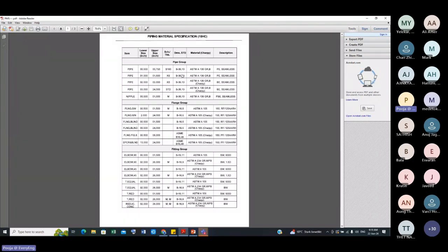And then I cannot just say I want to buy a carbon steel pipe, I have to be specific. So which pipe? As per the ASTM standard A, the designation A106 grade B, and how that pipe should be manufactured, seamless or welded. What should be the end connection? It is a plain end or the butt welded end, like this.